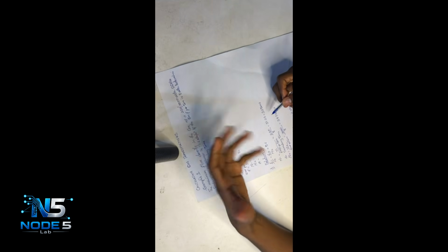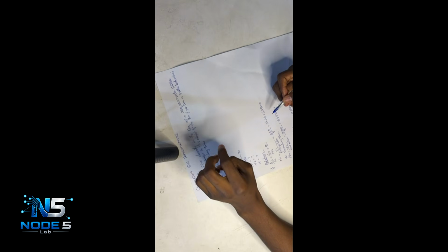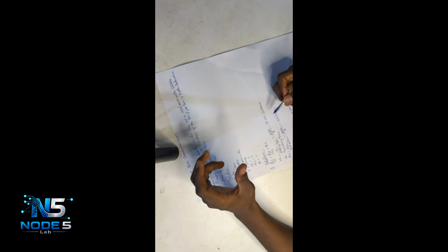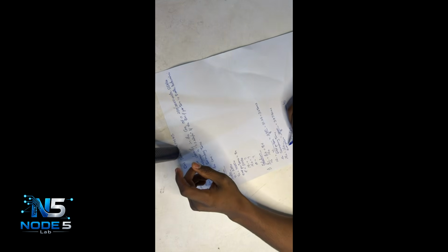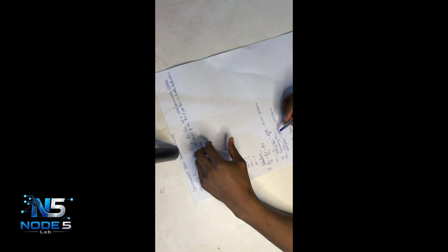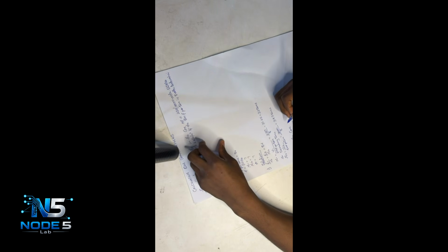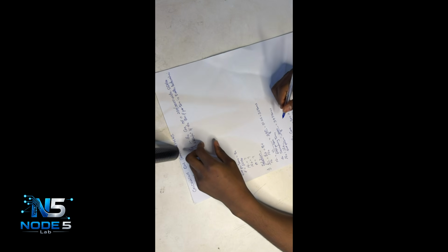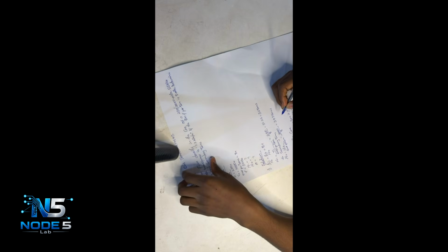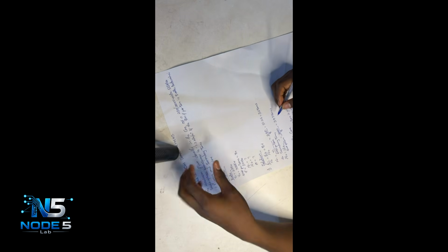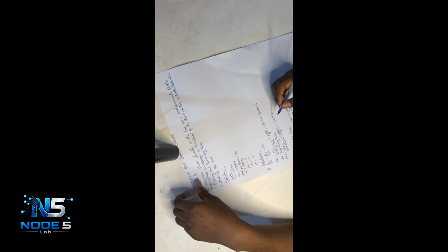The same thing that we did for the primary, we'll do for the secondary also. We state the formula N2 is equal to V2 over EMF per turn, which is the voltage of the secondary windings divided by the EMF per turn, which is 3000 divided by 8. That will give us 375 turns. Very simple like that. Good.